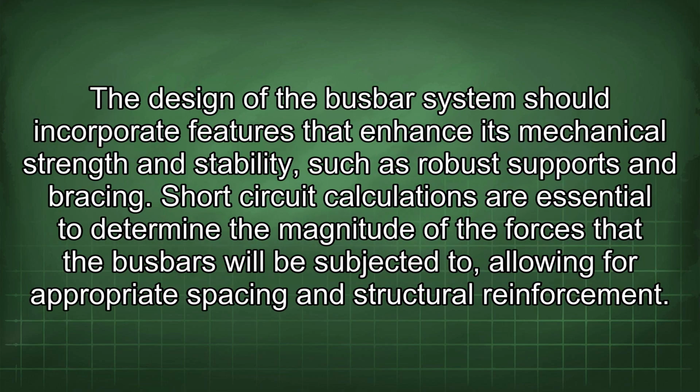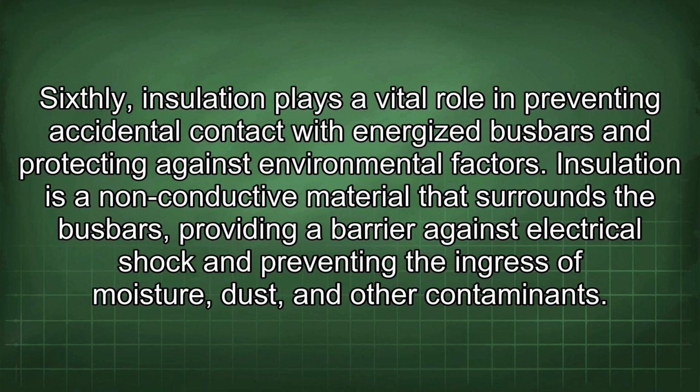The design of the busbar system should incorporate features that enhance its mechanical strength and stability, such as robust supports and bracing. Short-circuit calculations are essential to determine the magnitude of the forces that the busbars will be subjected to, allowing for appropriate spacing and structural reinforcement. Sixthly, insulation plays a vital role in preventing accidental contact with energized busbars and protecting against environmental factors.